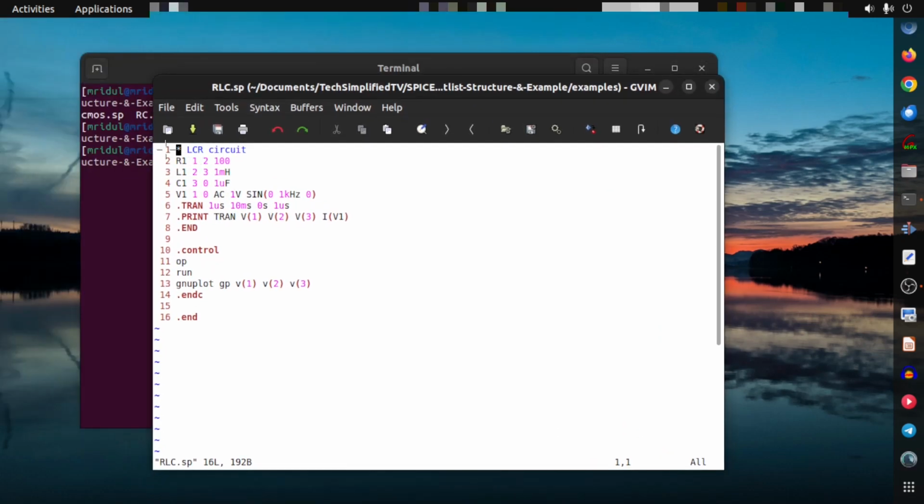So you can see here, these are the components, then it is the sine wave voltage, and it's the same because we have an end statement. Even the mistake is there. You can see the end. Let me remove this line by inserting an asterisk here. So the end will be at the end of this Spice deck. Everything remains the same. Let me close it and let me run it.